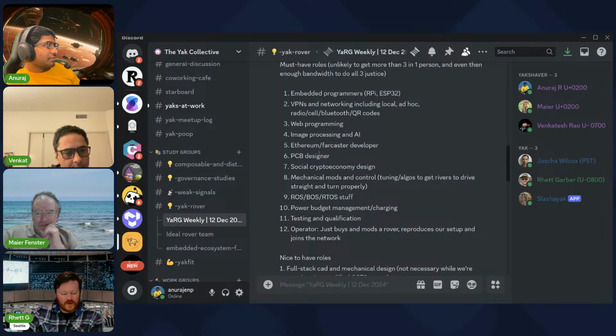Anything in the ARM world or the ESP32 world is 3.3. It's only the older Arduino stuff. So we should imagine a universe that's 3.3 volt digital electronics and maybe 6 or 12 volts for any motor-type parts, right? That's basically it.